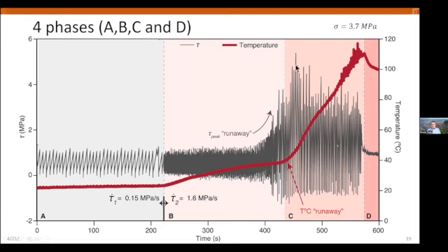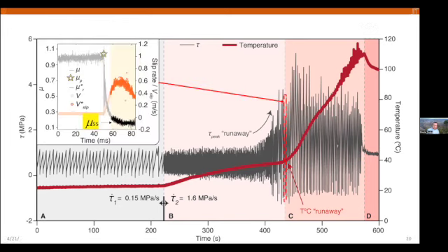This behavior of very high resistance goes on for a while, for roughly 120 seconds. And then suddenly you do have a behavior which is completely different. You start developing a very thick layer of melt, and that thick layer of melt is sustained, and the sample at that point deforms by creep. So there is not any more stick-slip behavior, but everything is deforming in, like, viscous shear. So now we are going to see one of these events.